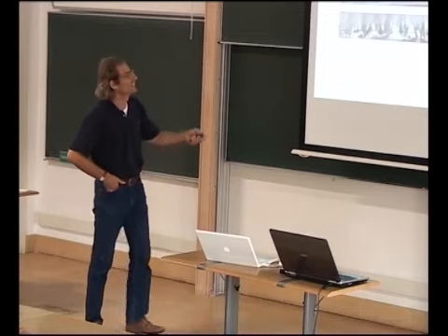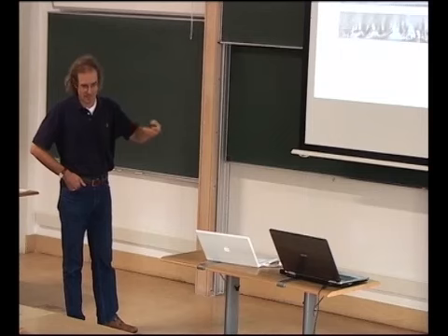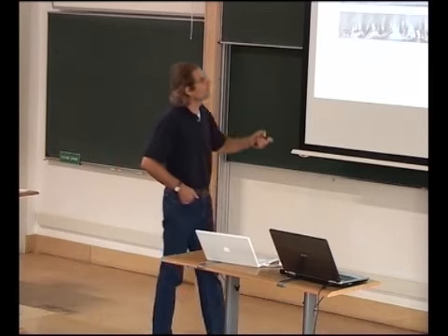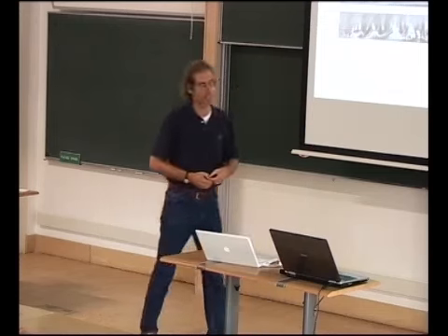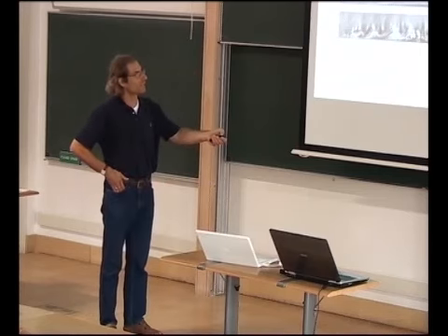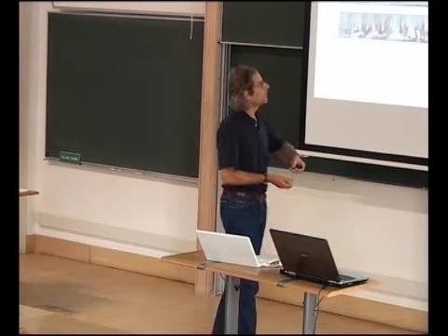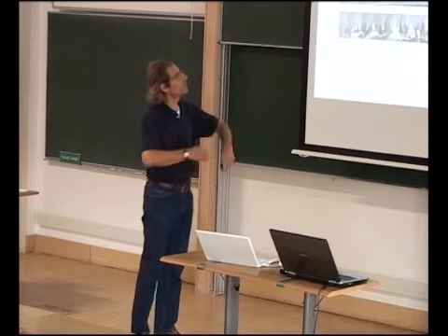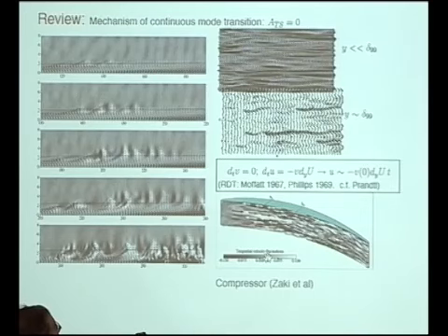Javier cited a paper in 1974, but it at least dates back, I learned it from Moffat's paper, and it also appeared in volume 1 of Annual Review of Fluid Mechanics, so it wasn't actually the algebraic instability literature, it was the rapid distortion literature. And rapid distortion theory explains why you can ignore dp by dx and come out with Prandtl's argument that velocity fluctuations are due to vertical displacements of mean momentum.